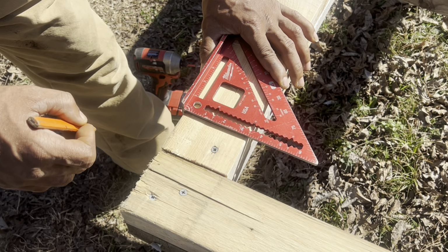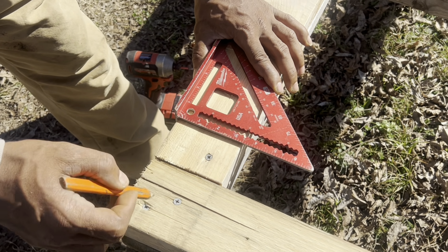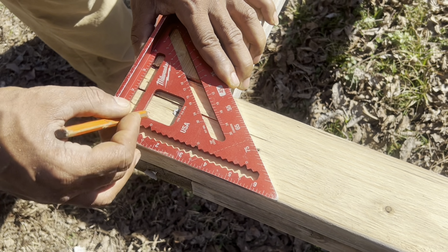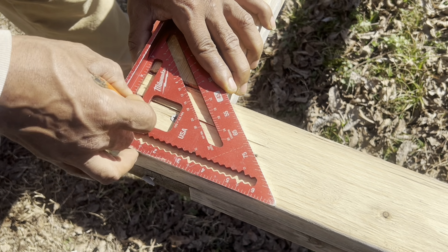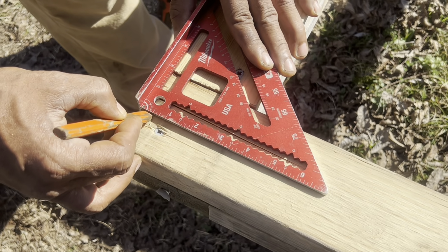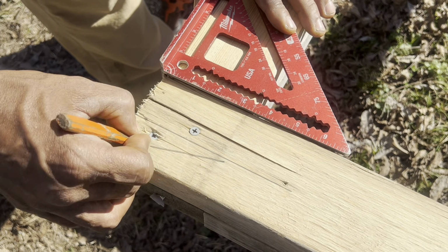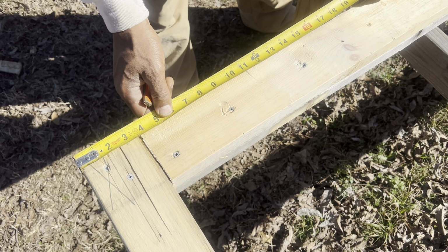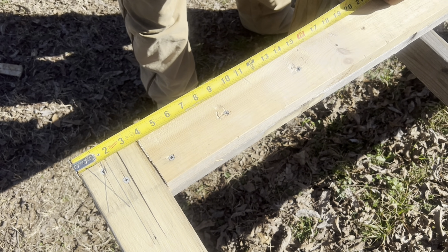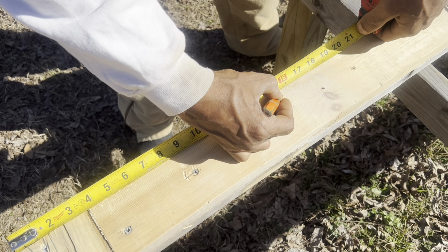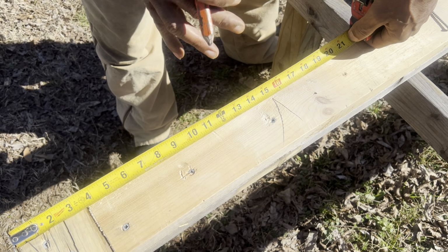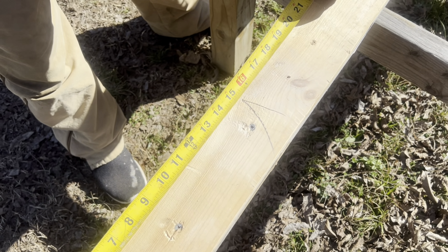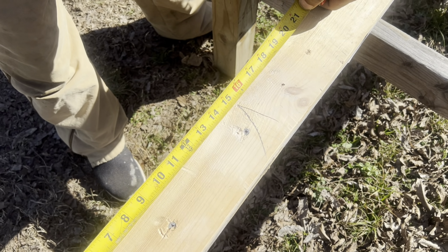Now, I'm going to lay out my rafter right here at the corner of my building. I just take my speed square, make it flush with my double top plate. I'm going to mark 1.5 inches. Right there. X marks the spot. Okay, now I'm going to measure from the corner of my structure 15.25 inches. I'm going to make a crow's foot right there. Now the reason I'm doing this is because I want my roof decking to break halfway on my rafter. And I'm going to show you what I'm talking about.